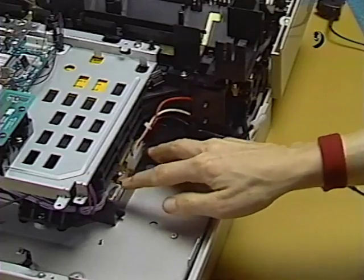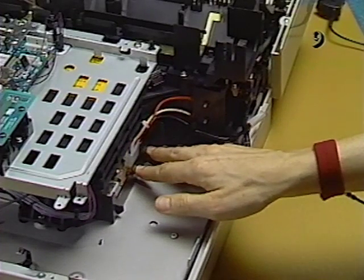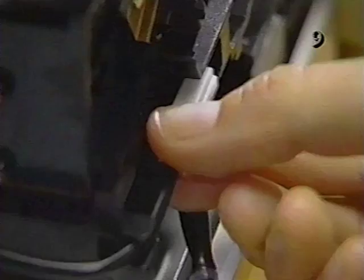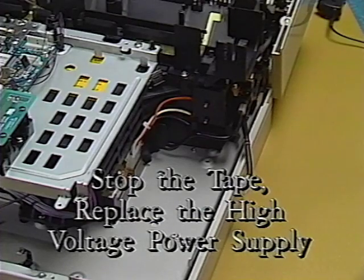Now slide the high voltage power supply completely under the scanner assembly so that the notches on the bottom of the tray fit into the slots on the printer chassis. Finally, reconnect the black cable to the high voltage contact assembly. Stop the tape and replace the high voltage power supply.